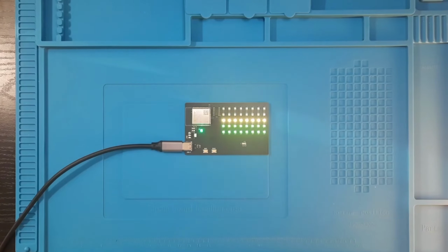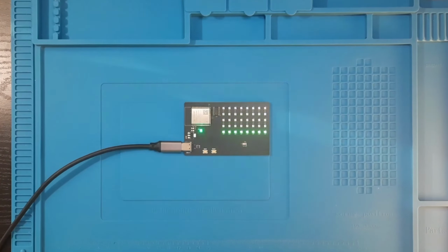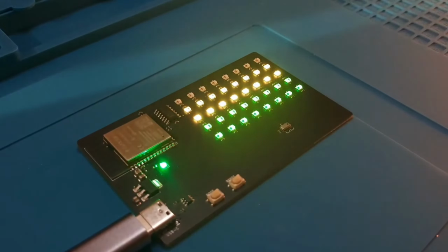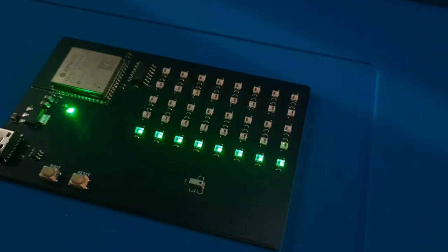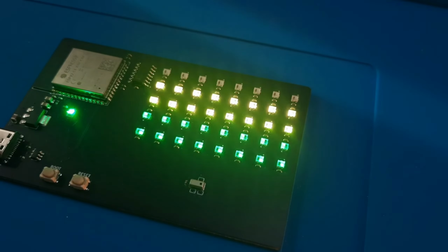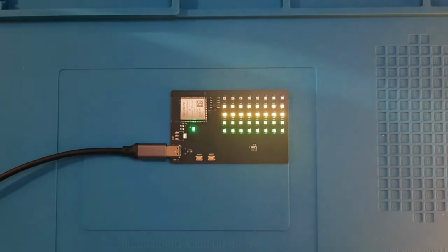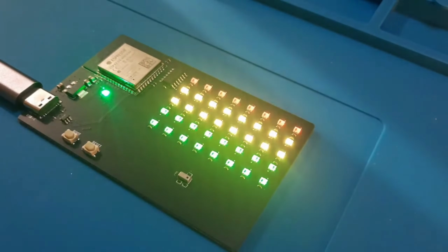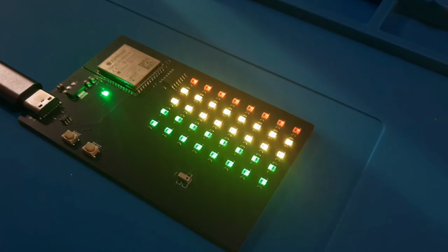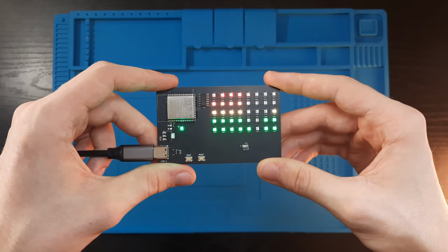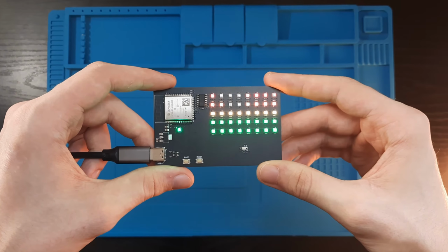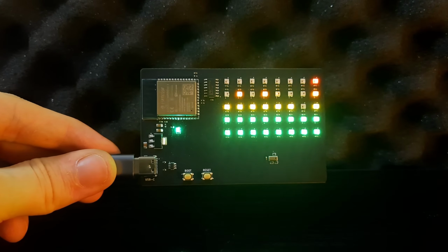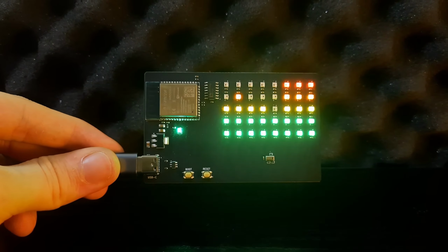When a volume over a certain threshold is detected, a full row of LEDs lights up. Technically, it worked. The display reacted to sound exactly like I wanted, but visually, it wasn't very interesting. It looked more like a volume meter than an actual visualizer. Instead of only preserving the current audio level, I wanted the display to preserve a little bit of history. So I created this scrolling waveform. The result is a waveform that continuously moves across the board. You can actually see the audio evolving over time instead of just seeing the current volume level.